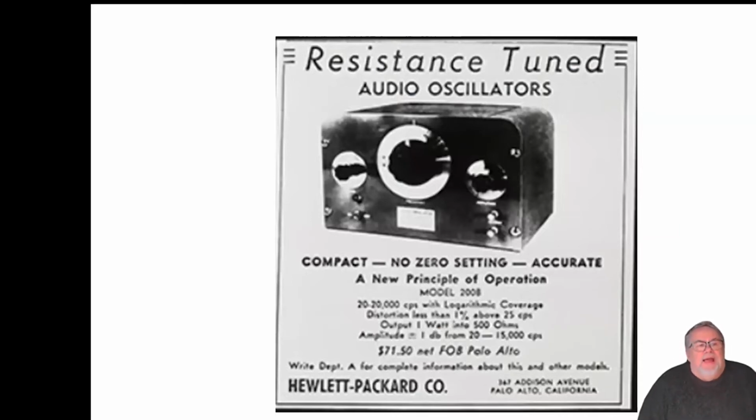In 1937, a guy called William Hewlett did his PhD at Stanford on nonlinear resistors in amplifiers. And it turned out you could make an oscillator that you didn't have to keep tweaking. So him and his pal, Dave Packard, started a wee company in their garage called Hewlett-Packard. And that was their first product, an oscillator based around having a bulb in place of a resistor. If you put a bulb in instead of the resistor, this thing no longer drifted and it stayed at the same frequency and the same output.